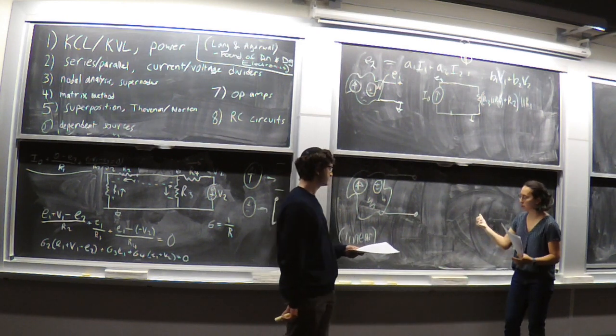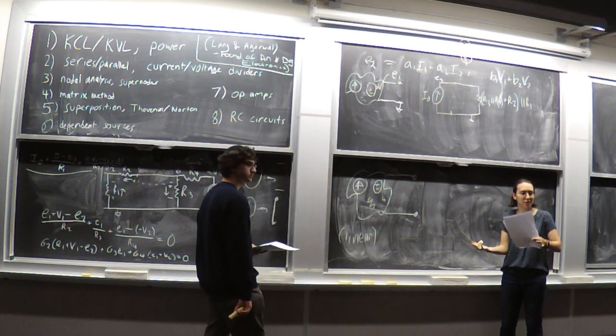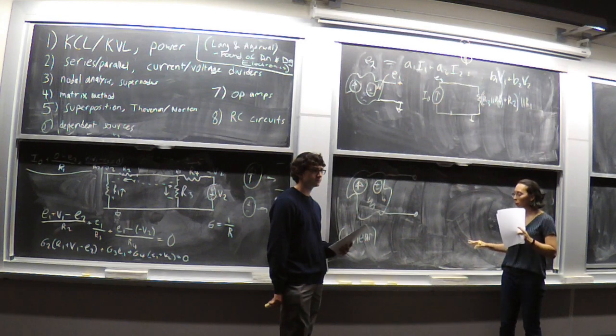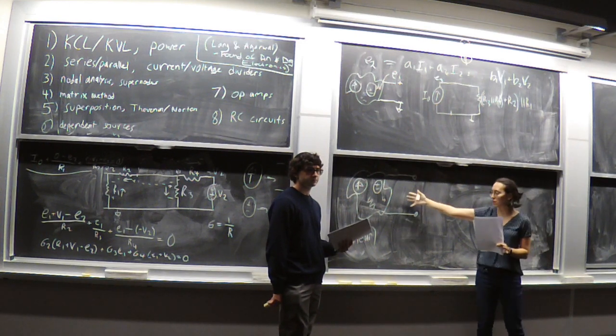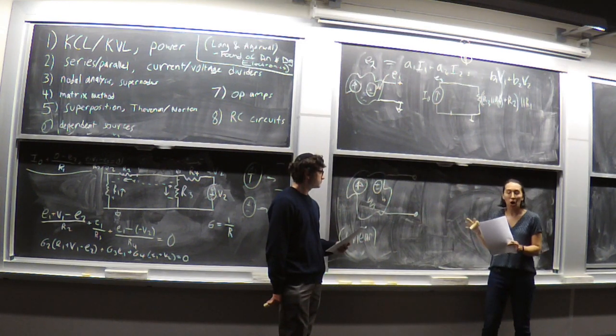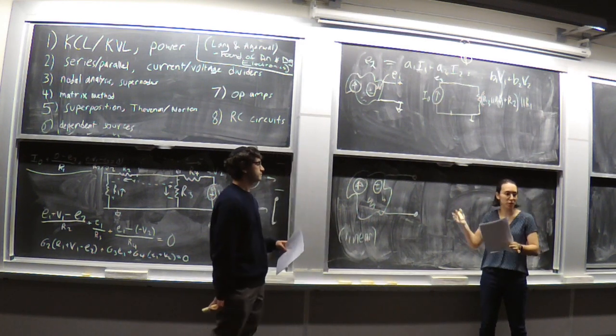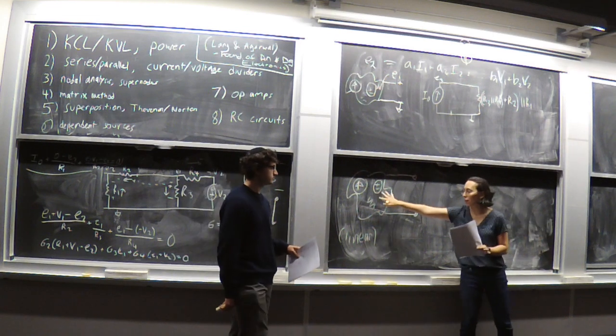So we'll start with the first method. Does that make sense, why you're characterizing the circuit by doing that? We just want to know how I relates to V. If we're going to use this device and attach it to something else, all we care about is what the voltage response is for a certain current, or what the current response is for a certain voltage. We don't care about anything in here.